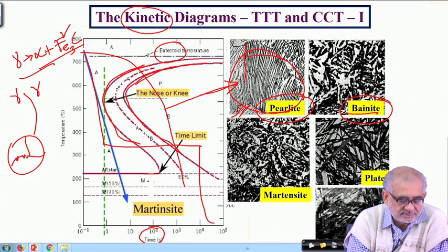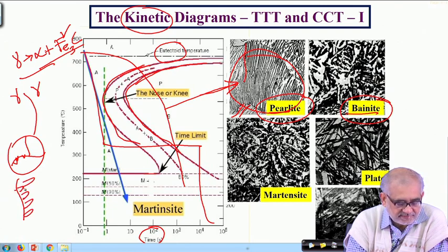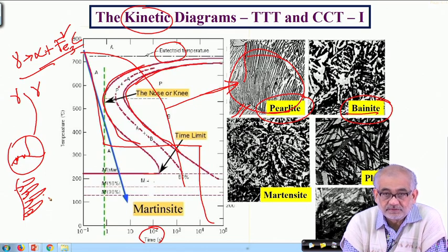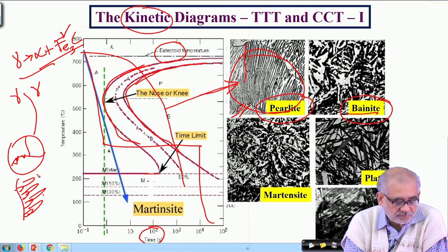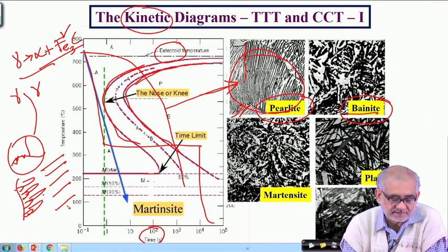certain nucleation of cementite, and this kind of a boundary will tend to move when you form such cementite lamellae, and when they actually grow edgewise, simultaneously the portion in between transforms to ferrite. So nucleation of cementite triggering formation of ferrite because of carbon depletion. So this is how we end up getting such lamellar aggregate, where the volume fraction of this aggregate is purely dictated by the phase diagram.